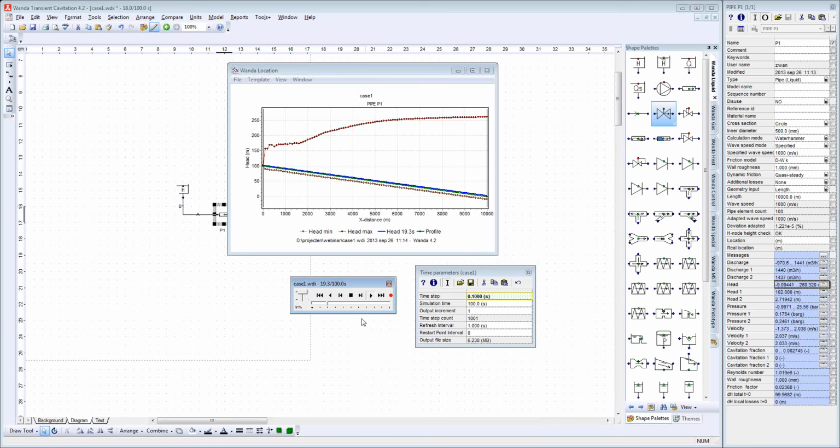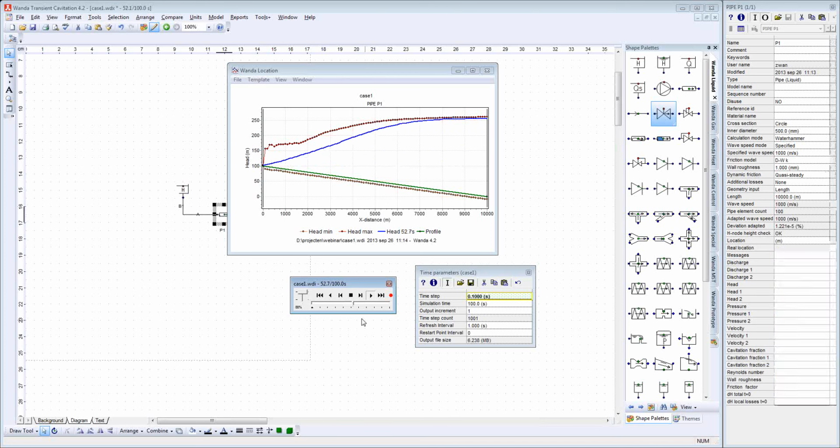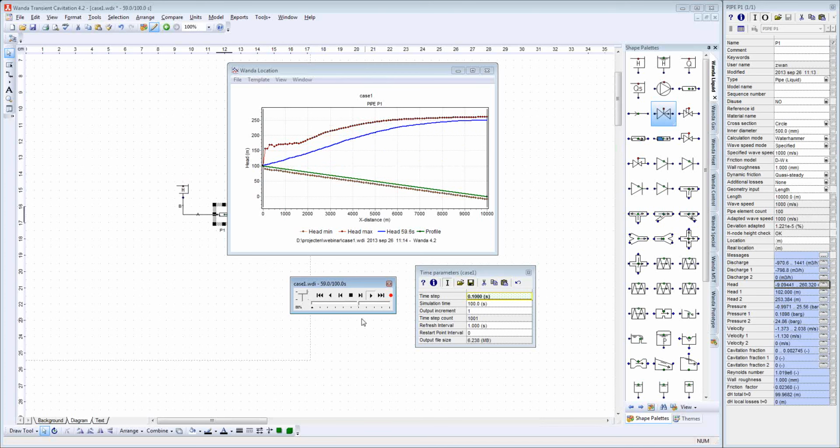Again, at the beginning, nothing is happening. Now the pressure starts to build up. The valve is closed, and you get the reflection on the upstream boundary. Again, a reflection on the downstream boundary, which results in cavitation. And the collapse of the cavitation, you can see that gives all kind of pressure spikes along your line. Now you get already much more detail, because now we have not 10 points, but 100 points along the line.